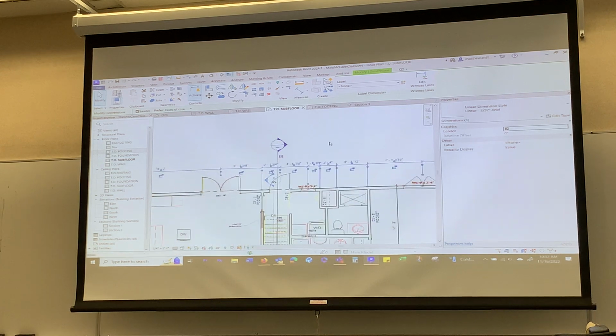You don't see a whole lot of residential drawings going to the 16th like that too much. We used to do it in here because the AT students used to learn how to use Revit like you are now using this house. And also because we were in pretty controlled conditions, that house was like a bit of a piano, like we built it pretty well. So we actually did use it, just so that people understood the theory. Because really the exterior walls on this thing are 5 7/8, so we thought that we should be going to an 8 at a minimum.